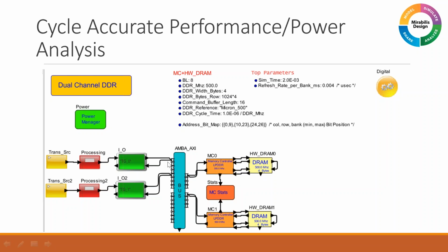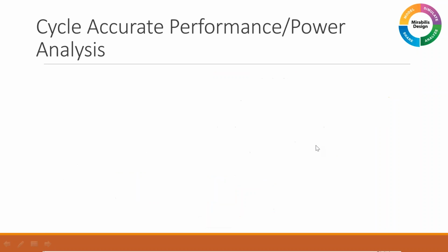So one of the things you can do is set up these different elements and have hierarchical buses. It can be a network on chip, could be an AXI, could be any of those. And you connect them into, say, multiple memories, and each memory can have its own number of banks, any number of banks. Oh, here we go. You can see the bitmap has, in this case, 3 bits, so it's got 8 banks each.